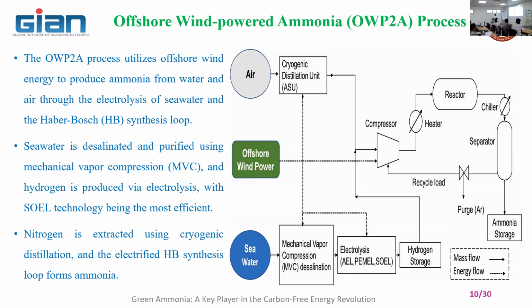This is the answer. Seawater has minerals and salt, which can corrode the components. To avoid that, you can extract the water through a solar desalination plant. You provide heat in the form of solar radiation. Due to evaporation, the saline water remains at the bottom, and the drinkable water, due to its low density, comes out. It is then used as water for producing hydrogen through electrolysis.